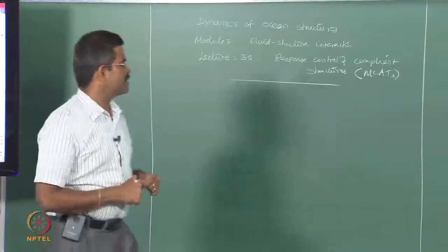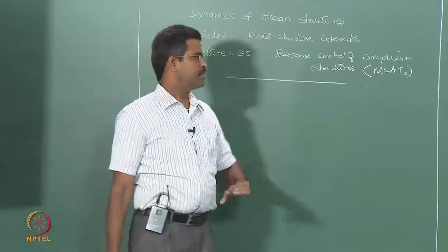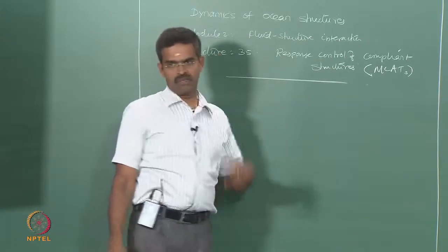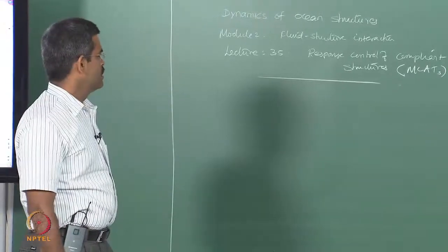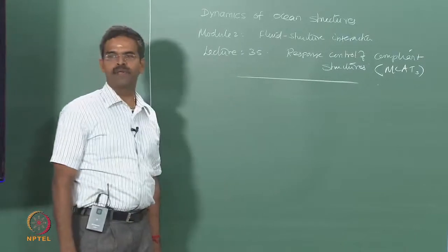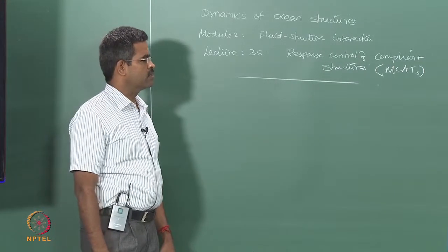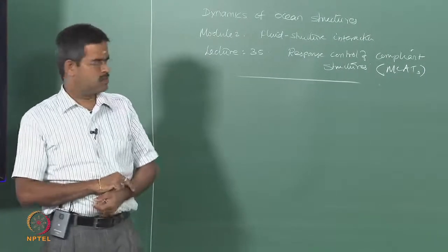So in the last lecture we started discussing the advantages of articulated towers and where they are being applied. We already said that they can be used for three main usages. One is as an anchor platform for transporting ships or vessels. It can be used as a temporary base in naval applications. It can be used as a pipeline supporting system or riser support system, which is commonly used.